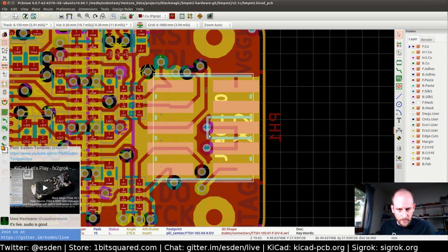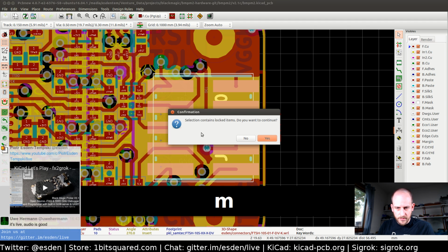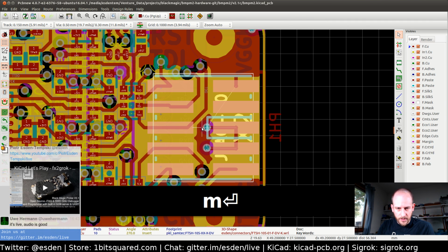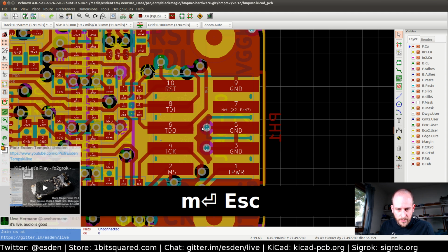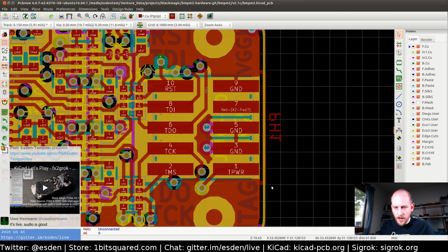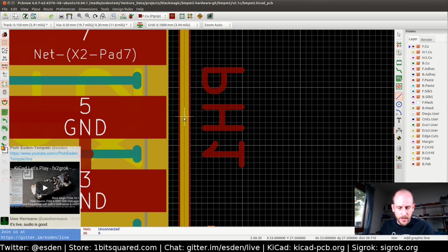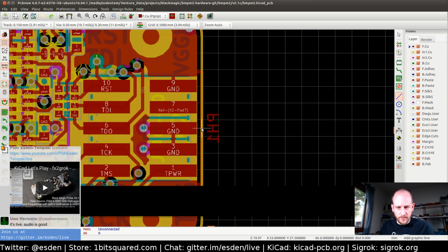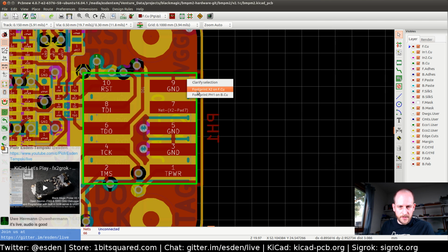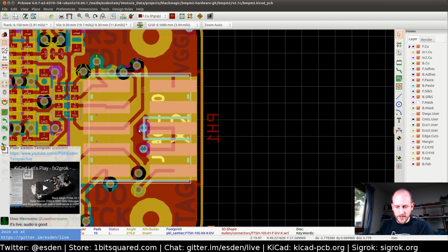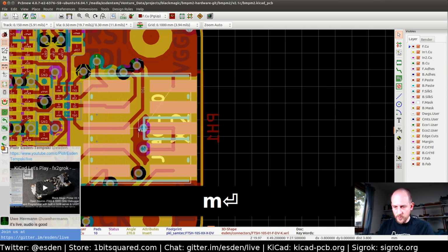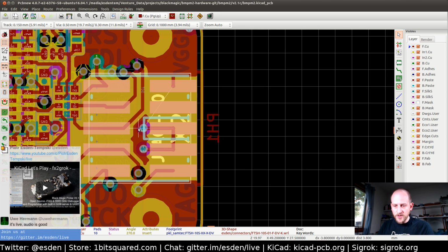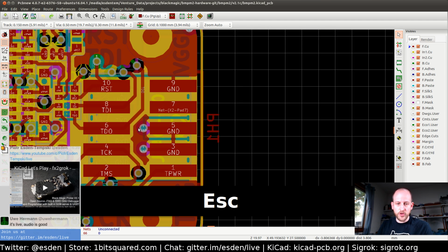Where is the anchor of this? Yeah, the anchor is here. Oh, that's the easiest. I probably should just go on the edge, reset the relative distance, and then move this footprint, and if I press move, the cursor will jump to the position. It's minus 3.8 millimeters. Okay, good to know.